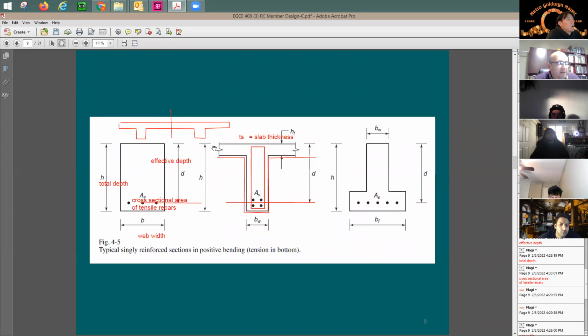And then you pour the concrete, and of course you have some reinforcing in the slab. So we are just simplifying it. We're not showing lots of rebars, right? Let's say you have rebars in the slab top and bottom, and you have the beam top and bottom, and then you cast the concrete all in one shot. So we call this monolithic. Monolithic means that they're going to be acting as one piece. Good question. Thank you.